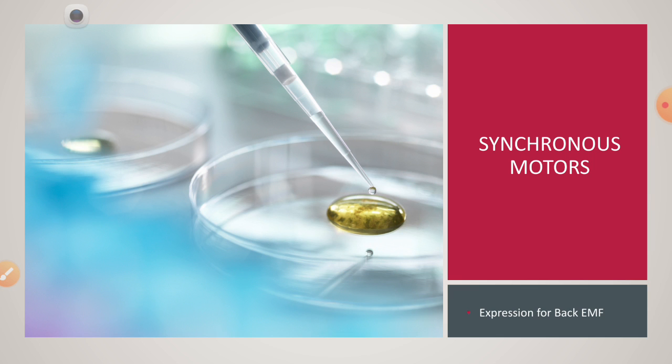In this case, we know the equation for the back EMF. It is equal to the square root of the square of the terminal voltage plus the square of the resultant voltage, minus 2 into V into ER into cos theta minus phi, in case of lagging power factor.